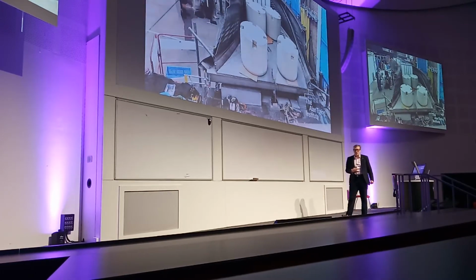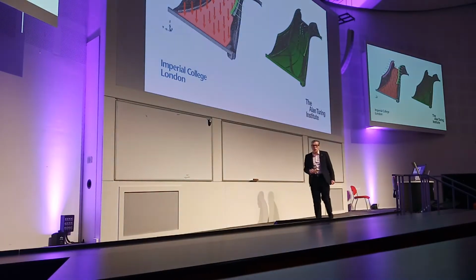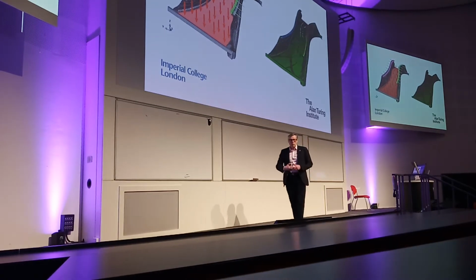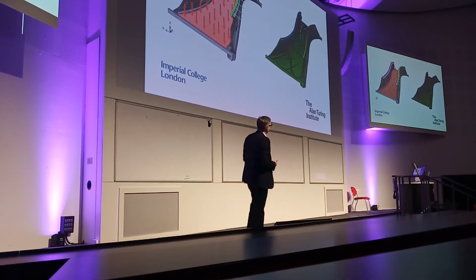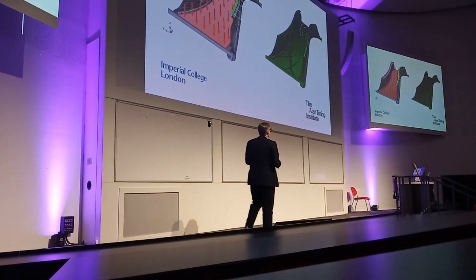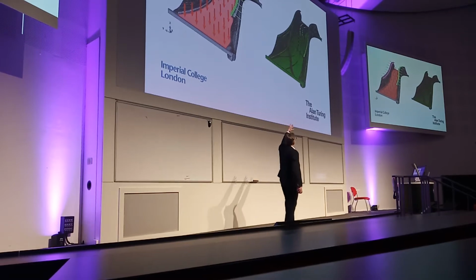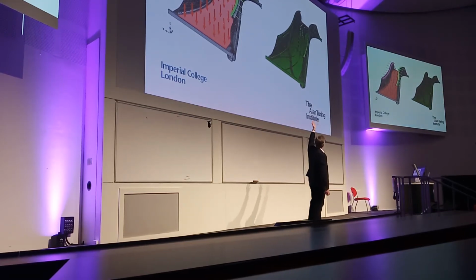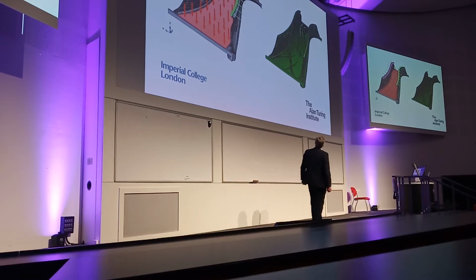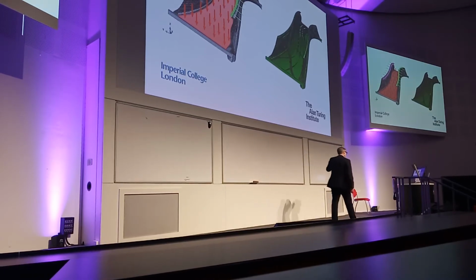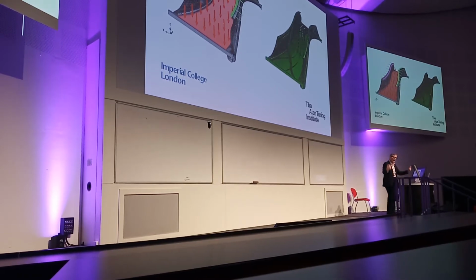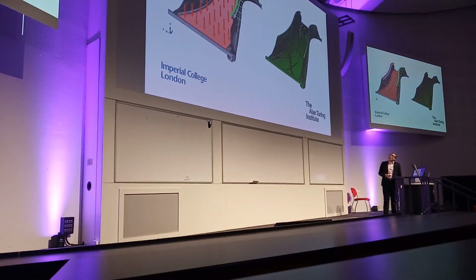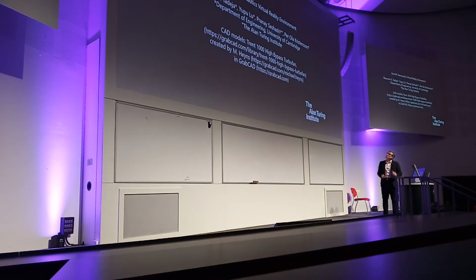It does deform plastically at some loading, and we were able to use advanced modelling methods, in this case finite element methods, which have been developed to not just solve the mathematical equations that govern the deformation of a bridge like this, or a structure like this, but also to assimilate data from the actual physical, its other twin, if you will. So this is really exciting work.